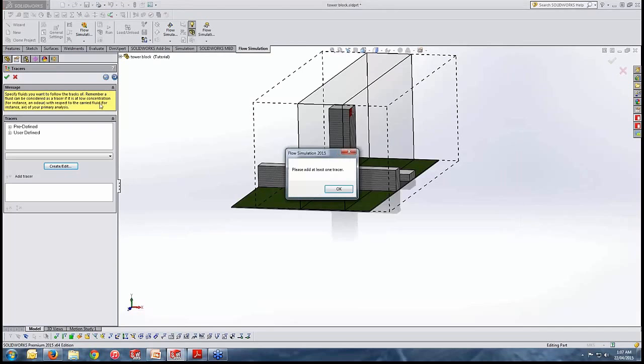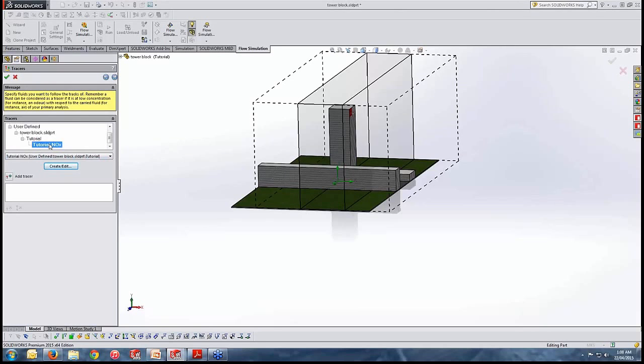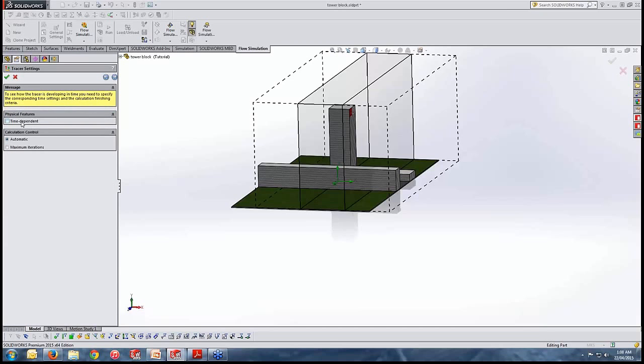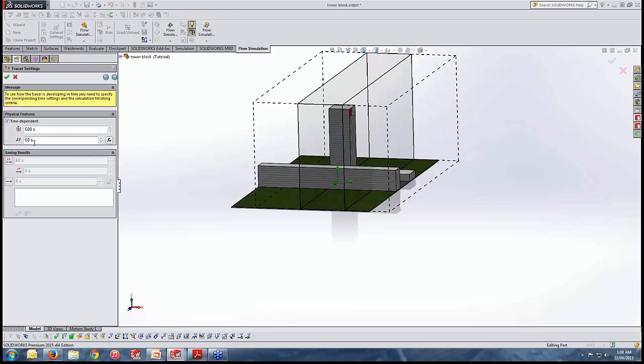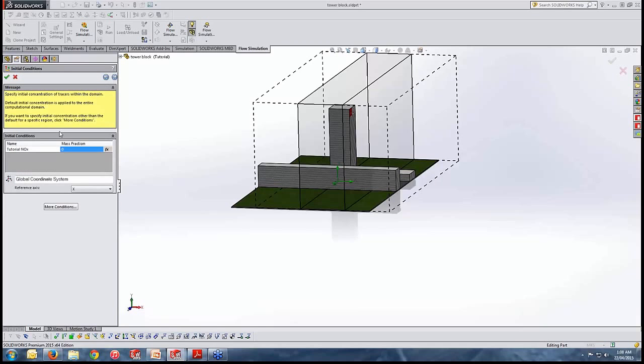Next, I have to say this needs to be added, add a tracer study, and go next. It could be time dependent, and for what sort of time frame, and saving the result with what scheme, clicking on next, and the mass fraction is what we have to assign here. Well, we are assigning the values as we agreed, 0.8 something for the value, and simply let me assign,